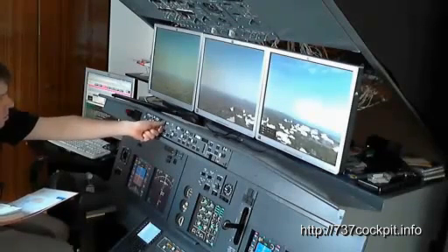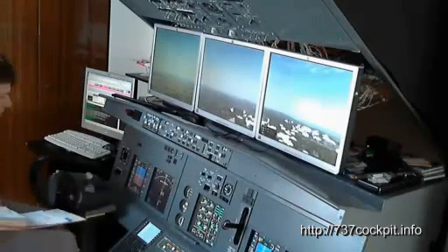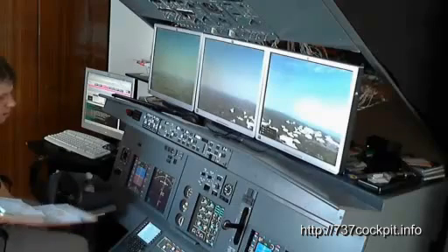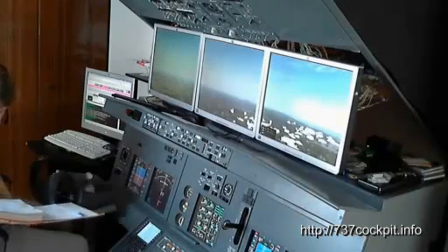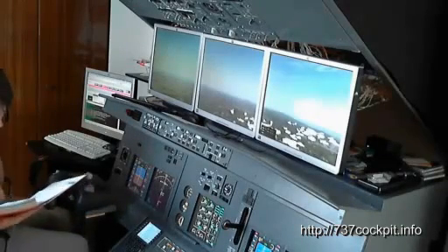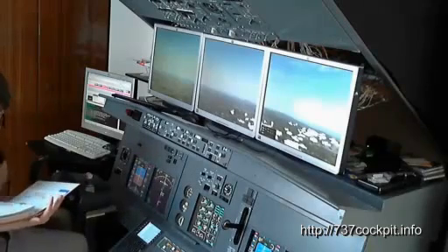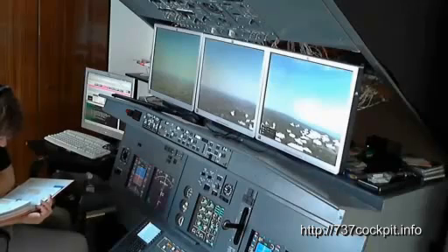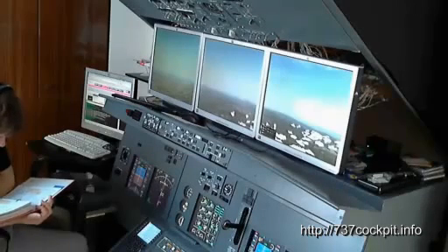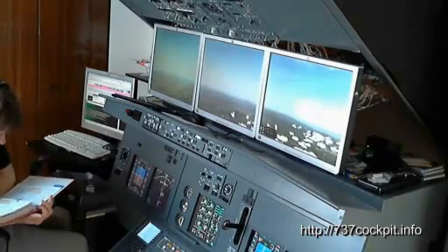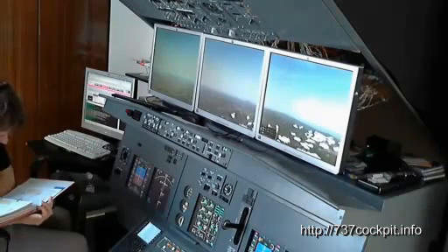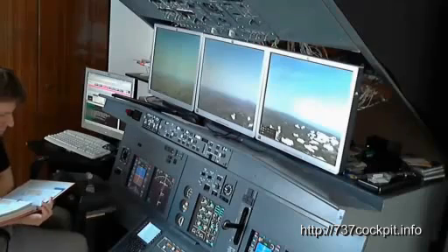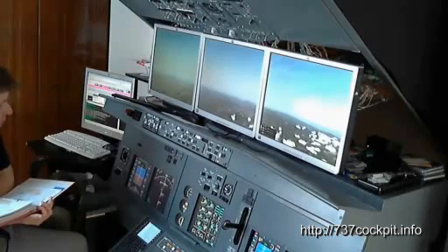As we are not expecting any clouds or fog, we will do only an ILS single approach. That means we will perform a manual landing. ILS 11 Yankee is an approach where, in case of missed approach, you will turn right at the Whiskey point, so you won't cross the runway 16 for landing.